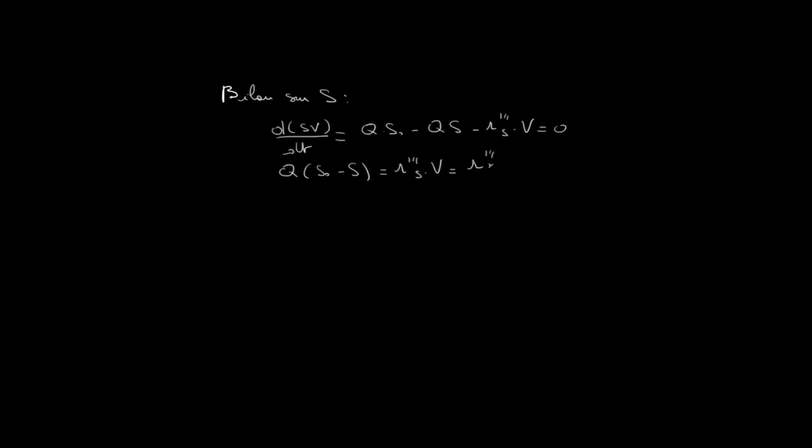We can replace R'''S by R'''X over Y_XS, and we can replace R'''X by mu times X. We make appear in this equation Q over V to make appear D, because Q over V is equal to D, and we can simplify by mu because D is equal to mu.